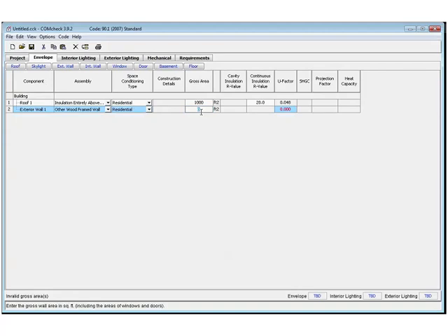I'm going to put my square footage of that wall in. Height times length of the exterior wall. That would include all windows and doors, is how you'd run the takeoffs. And then you see you don't have the option for insulation here. Same would apply if I did roof and I choose other. I wouldn't have the option to show my insulation value. You only have the option to show your overall calculated U factor.